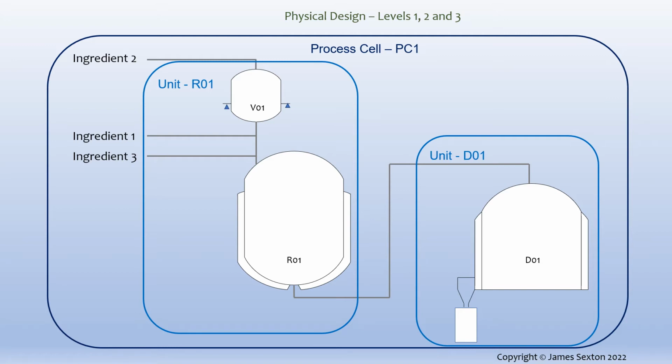It's defined as a functional group of equipment that can carry out a finite number of specific minor processing activities. Examples of minor processing activities given in ISA-88 are dosing and weighing. Also, according to ISA-88, an equipment module is typically centered around a piece of process equipment.